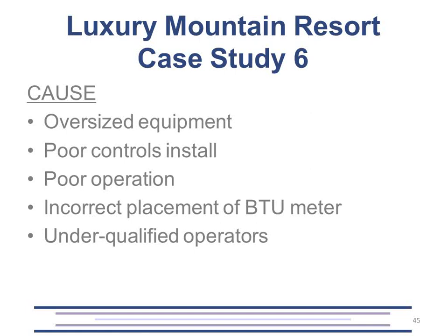Making things worse, the snow melt system, which keeps the sidewalks and street completely dry, was providing heat for the resort as well as the local municipality. The resort was to sell a portion of the heat that went to that municipality based on BTU meter readings monthly. However, the BTU meter had been installed on the wrong pipe, causing the resort to underbill the town by $90,000 per year for 2 whole years.